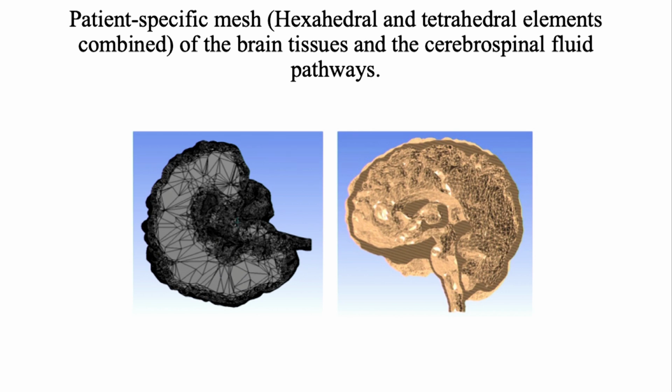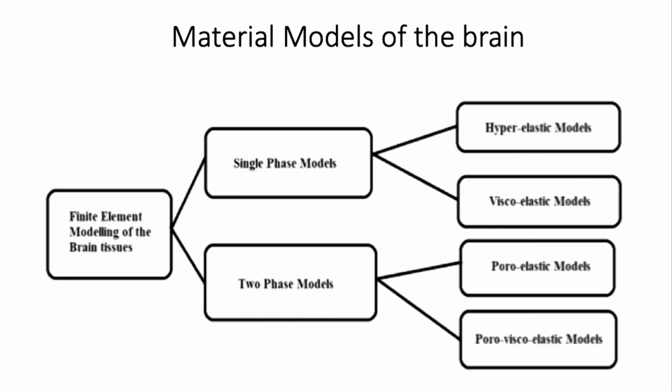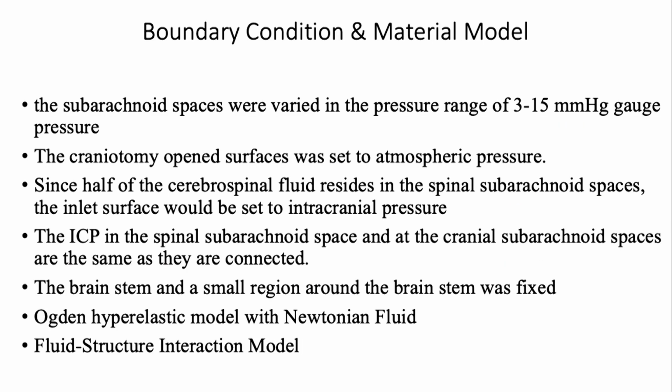There is a fluid element. So we solve two equations, and we have a boundary condition with the stem of the brain fixed, and we also have a pulsatile flow of the CSF which comes out of the arterial flow. That has been modeled, and the material model we have used here is a hyperelastic model. The boundary condition requires some understanding of the fundamental physiology, but nevertheless,